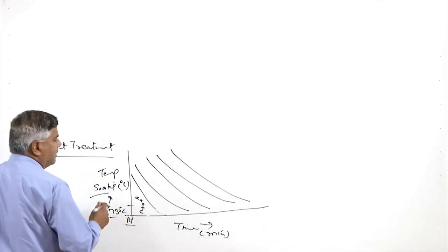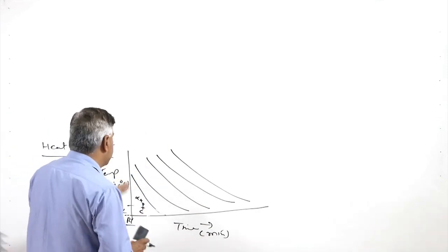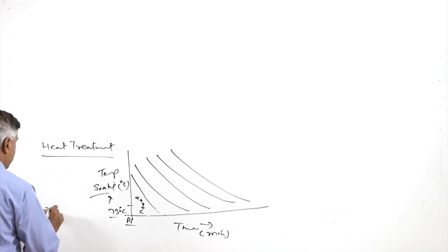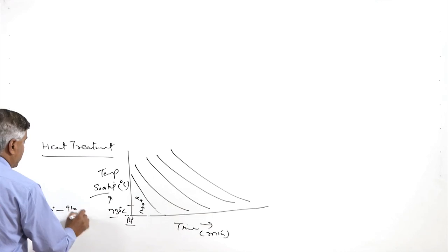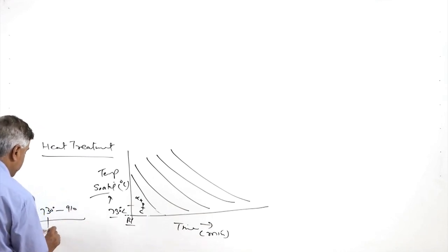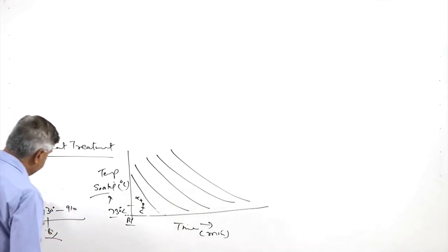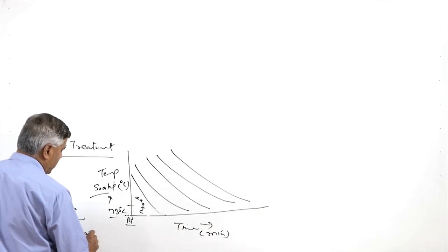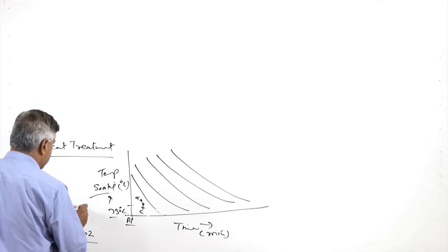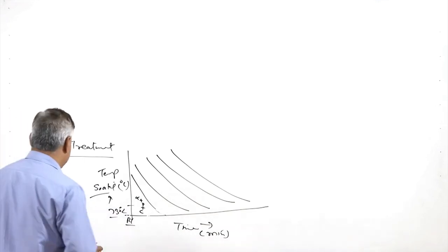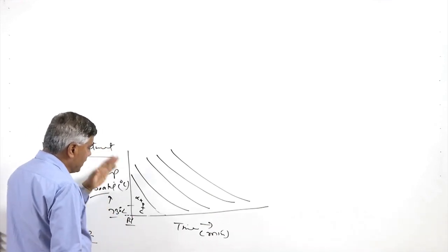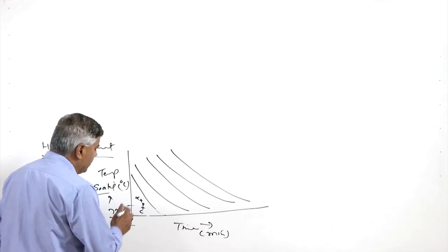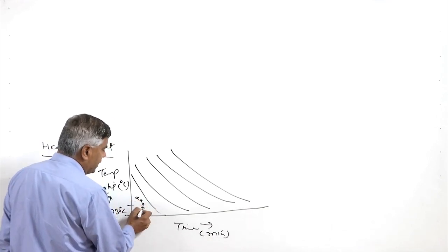So, when the steel is held for some time above the upper critical temperature limit, like say 800 degree centigrade or more, which will range from 730 to 910 degree centigrade depending upon the carbon content, for 0.8 the upper critical temperature limit happens at 730, while for very low carbon content like 0.02 or even less, it is 910 degree centigrade. So, whenever the steel is exposed to a higher temperature above the upper critical temperature limit, initially at room temperature, what does it have? Alpha, pearlite and cementite.